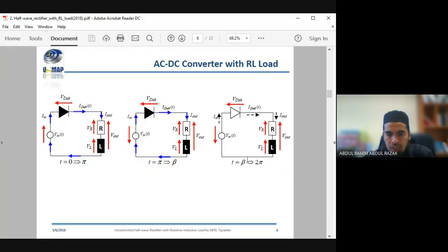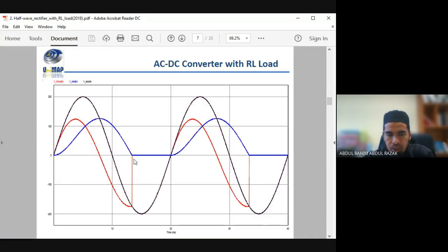Only after that will it block. The current has already entered the 0 region or crossed the 0 crossing. So at that time, current is 0, but the voltage will be blocked.